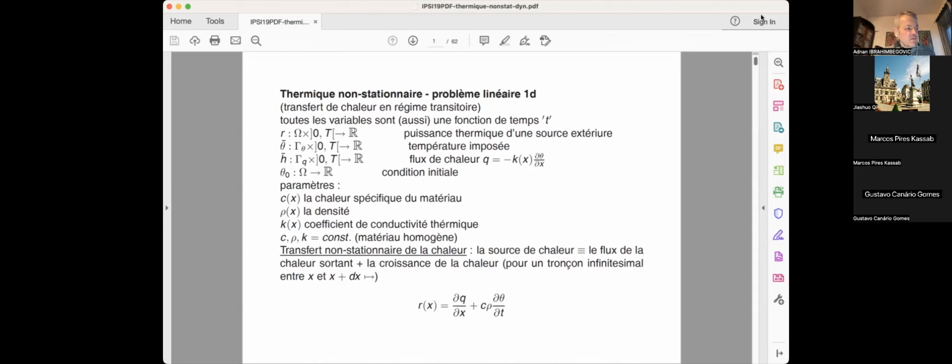And also, when you make more refined models, something called the structures, where on top of the continuum mechanics you put some kind of other kinematic hypothesis, so you can reduce the number of unknowns. Typically, for example, for a beam, you say that the cross-section doesn't really deform, so that can describe the displacement. These are the particular cross-section displacements of a particular neutral axis. And you can then do the thing in a way which is more efficient, and also, for example, for plates, shells and so on and so forth. So all these transitions will hopefully be addressed today.